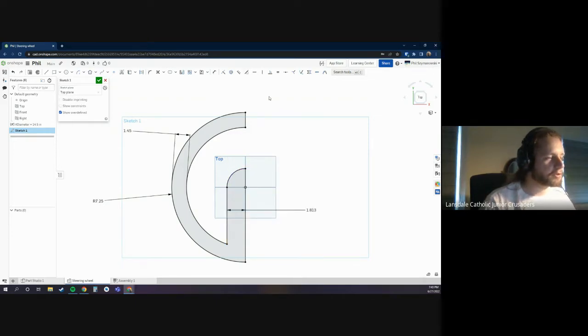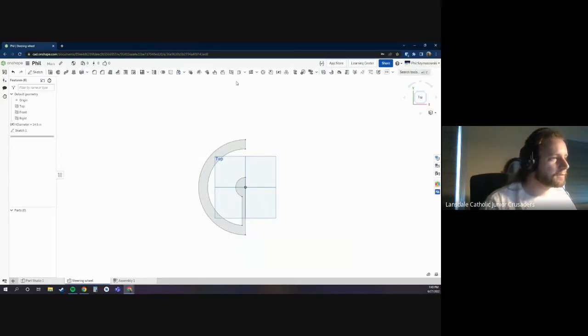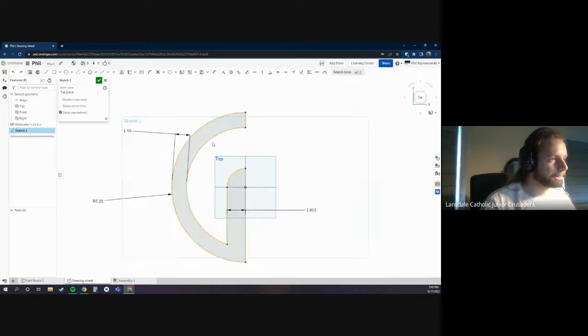Tangent. Be sure to use your constraints effectively. Think about your lines of symmetry and how you can minimize the total number of lines you need to sketch.